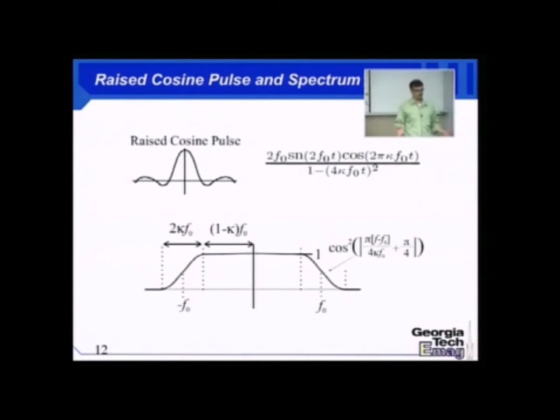So this whole field of communications engineering is called pulse shaping. If you ever see a section of that in a communications book, they're just basically saying tweaking pulses in the time domain so that they satisfy Nyquist ISI and they fit within my spectral constraints when I modulate it up to a carrier.